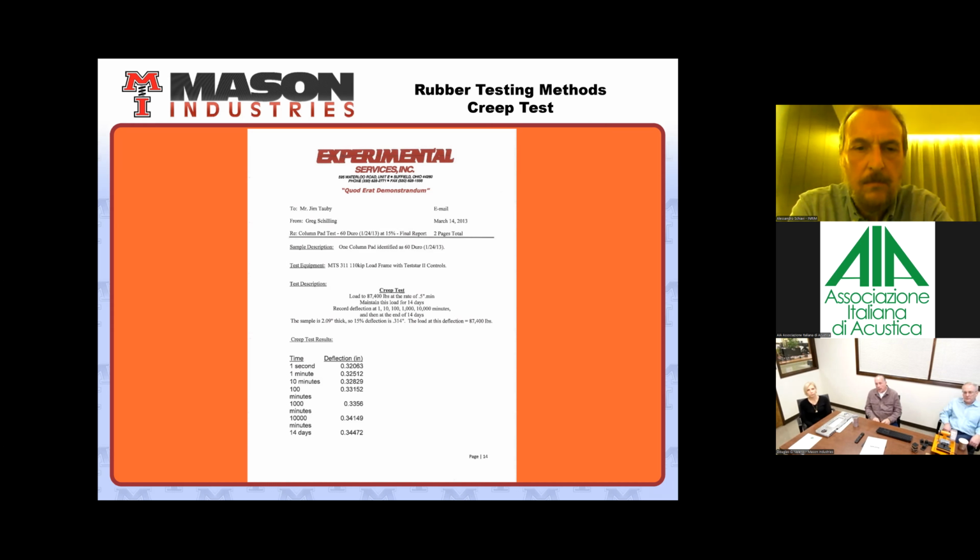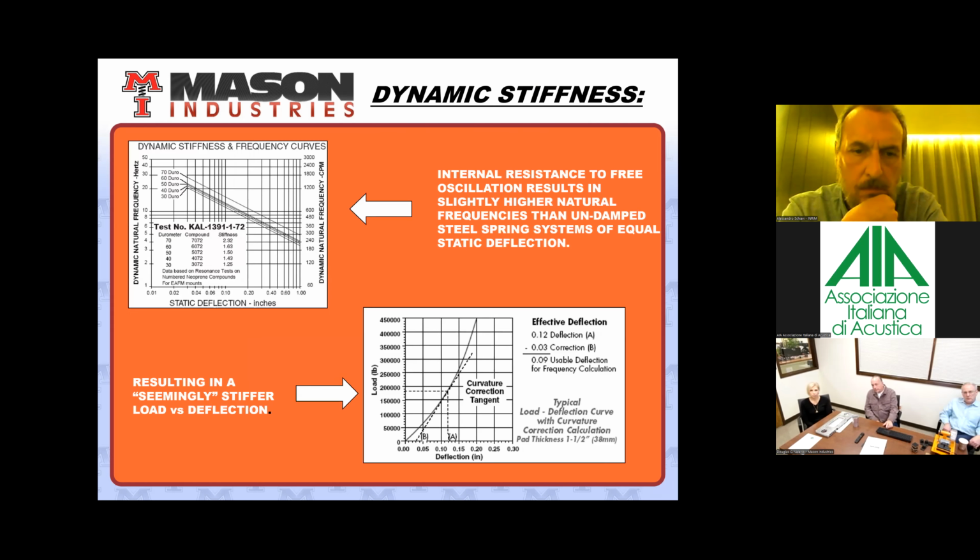And basically what happens, it's in decades of time. So you want to get 100-year longevity without any additional settlement. And basically we're working in the thousandths of an inch or mils in this case. So the idea is we don't have a lot of additional settling because of that low stress, low strain requirement.